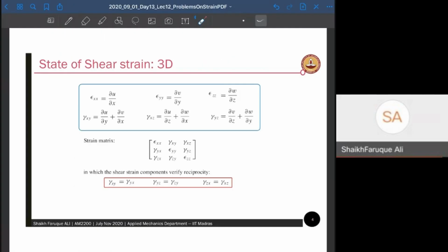We all discussed this, and then we said that there is a point strain that you need to understand, where the length is in the limit going to 0. So you don't consider a finite length here. What you consider is a very small, infinitesimal length. If it is an infinitesimal length, then you get down to derivatives, and these are the formulations that define your strains with respect to deformation. These are called strain deformation relationships. Please note that it is commonly known, and always defined, as strain deformation relations.